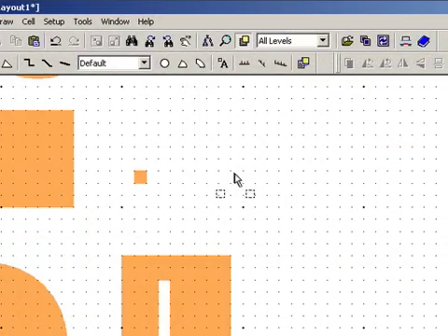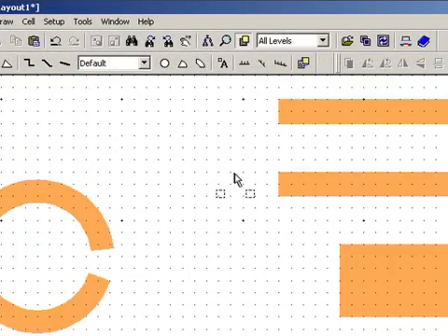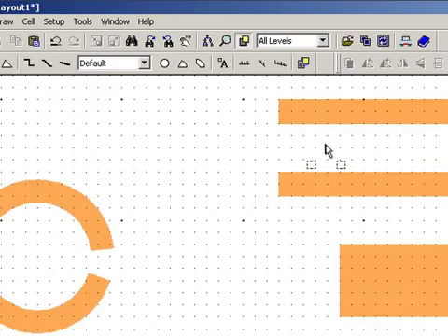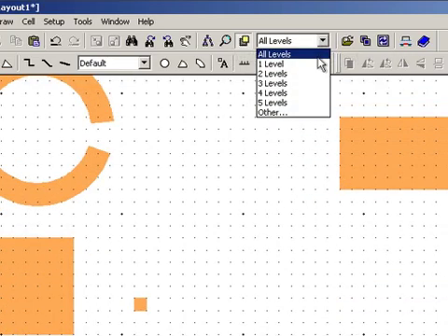This drop down button here and this button here allow you to show or hide various depths of your hierarchy. Now this can be useful for rendering speeds and efficiency. So for example, if you have a design that is quite dense with a number of instances, you can decide to only show certain levels.